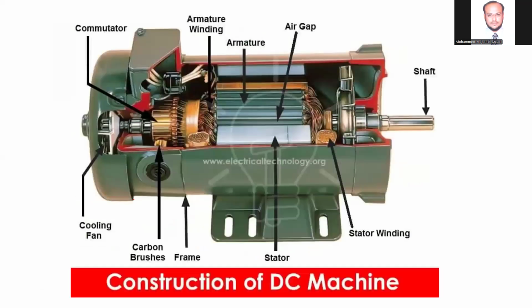So now this is the complete picture of the DC machine. This is the rotor. The rotor carries the armature winding, which is connected to the commutator segments. These are the armature conductors, coming from the slots over the periphery of the rotor and connected with the commutator segments. So this is the complete commutator. These are the bearings, end rings, and the fans.